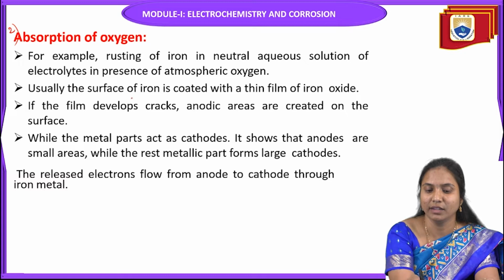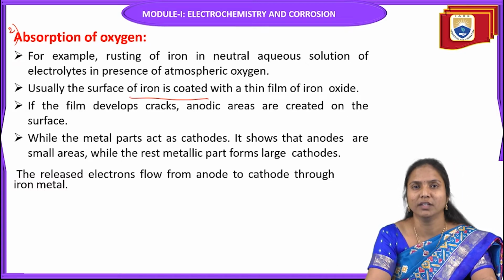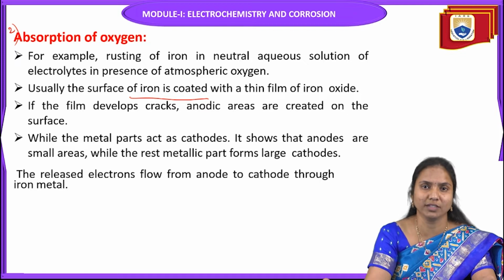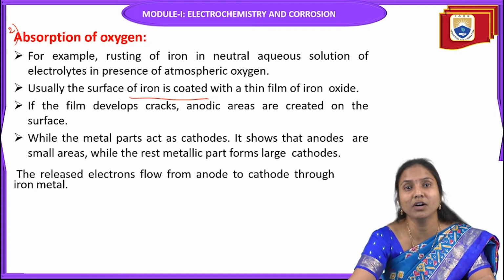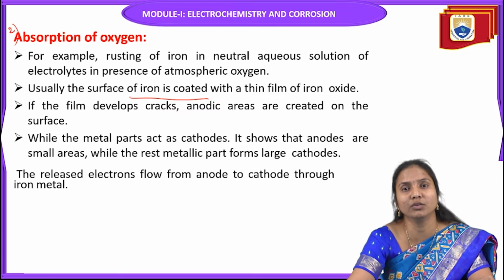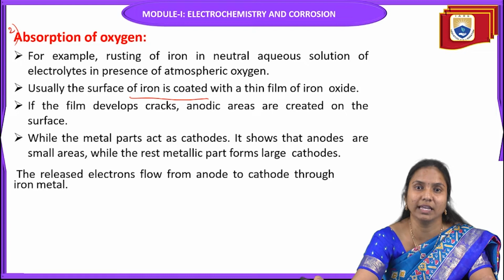Usually the iron surface is coated with a thin film of iron oxide. So this absorption of oxygen type of reaction occurs in a neutral medium in the presence of oxygen. Neutral medium is, for example, water or aqueous NaCl solution. When the metal contacts this neutral medium in the presence of oxygen, iron metal interacts with atmospheric oxygen and forms an iron oxide layer on the metal surface.